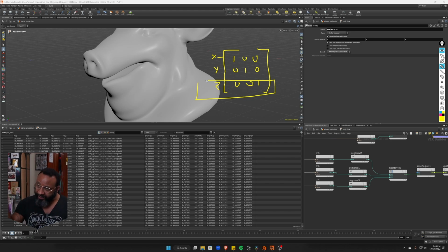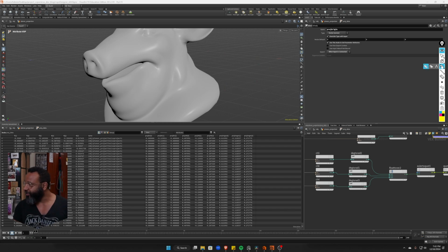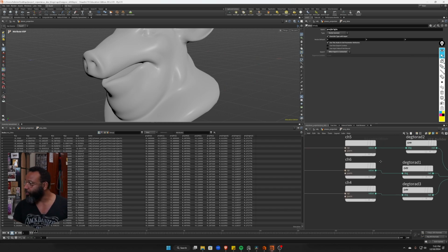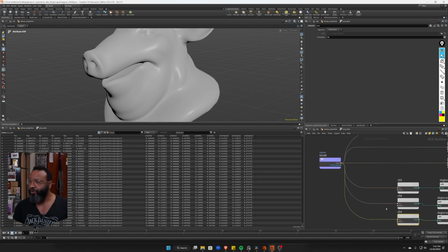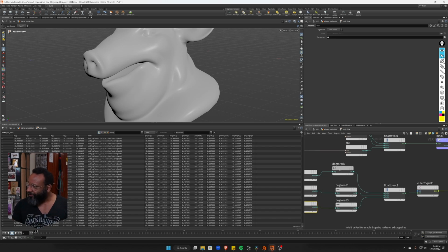So I need that vector. That's what I'm trying to get to right there. All right, so how do I do this? First thing, just like I did with my translation, I fetch my Rx, Ry, and Rz, and then I plug that name in there so that connection is dynamic. I actually forgot to do this the first time, and I was getting really wacky results. Along with Euler rotation versus 3x3 matrix rotation versus quaternion rotation, there's also degrees and radians.